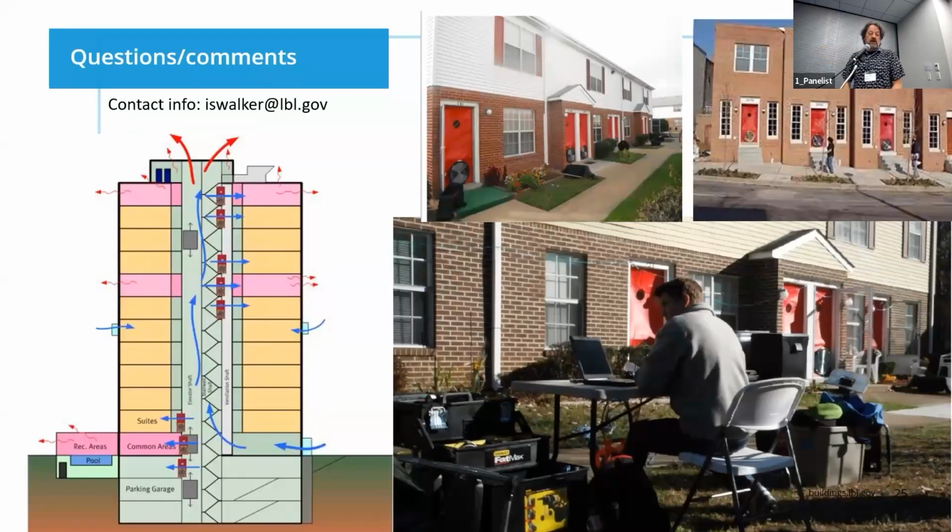And I'll stop there, and I will just conclude with saying that this is still kind of a new thing. We've sort of got used to the idea of measuring the air leakage of exterior envelopes, translating that into an energy usage, translating it into an air exchange to dilute contaminants. But thinking more about what happens inside multifamily buildings, I think is going to be super important. You can definitely control energy, and you can definitely control the transport of contaminants.